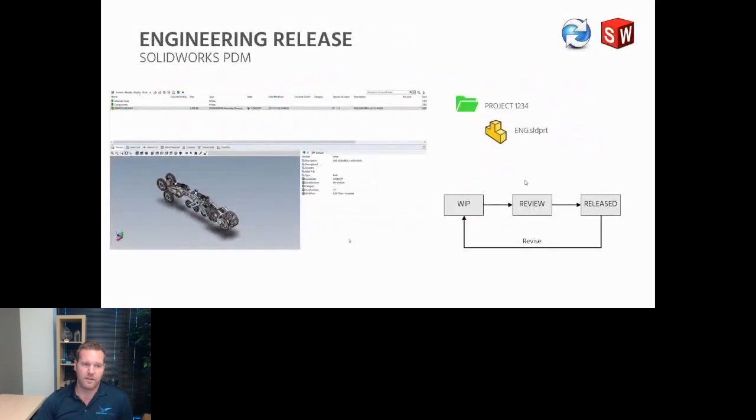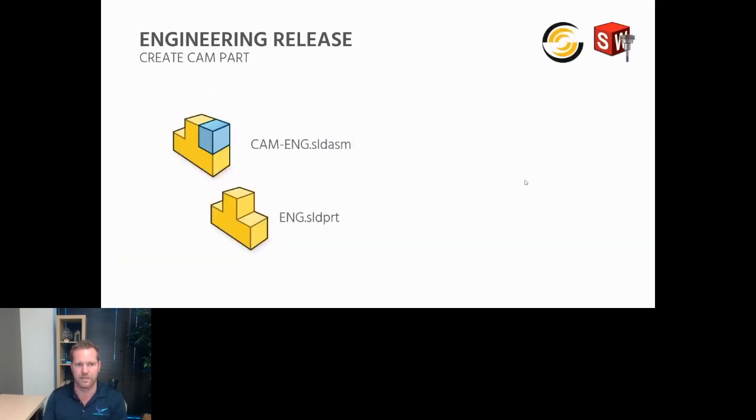First, hitting on PDM again, the standard workflow that companies will use is just in PDM. Here I have a simple workflow setup that uses a work in process state, a review state, and a release state. It's very common to work out of just Windows Explorer, right-clicking, changing the state on that file, moving it from work in process through review to the release state, while realizing all of the other benefits you get out of PDM.